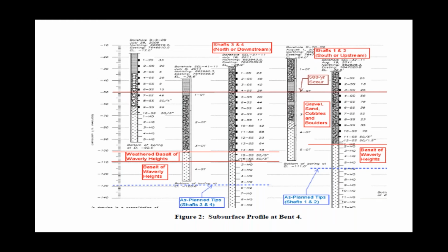So in some of these borings, it shows a 20-foot socket. Well, if you hit rock in some of the other borings, it's more like a 50-foot long rock socket, okay? And again, we're talking 10-foot diameter shafts over water working from a temporary trestle. So that's no small undertaking. I understand the design perspective of covering yourself with the worst case scenario, but that's only conservative for design. In fact, it's very risky for construction, and really that's where the real money is.